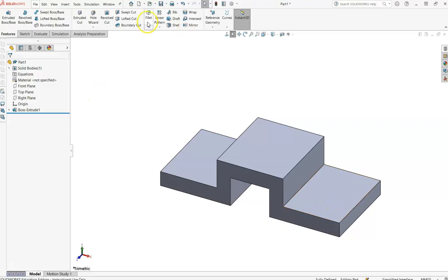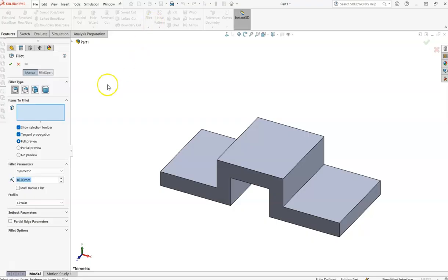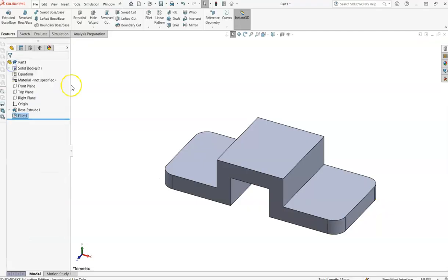So I'm going to get my 3D fillet on the Features tab, and it shows in the bottom corner of our picture, it says 4x radius of 6. So 4x means it's 4 different times, so it's all 4 of these corners. Just carefully go through and click each one of the lines, and we can hit the green check.